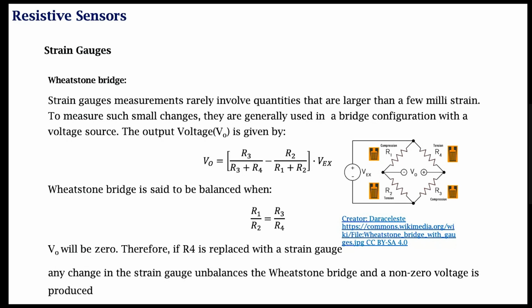Now, depending on where you are applying, you could relate the change in the voltage to the change in the resistance. Usually, the measurements of interest are of the order of several microstrains. Very rarely we go to the range of millistrains. To measure such small changes,